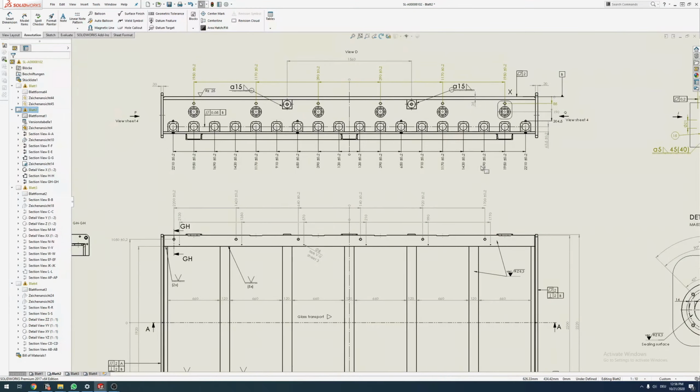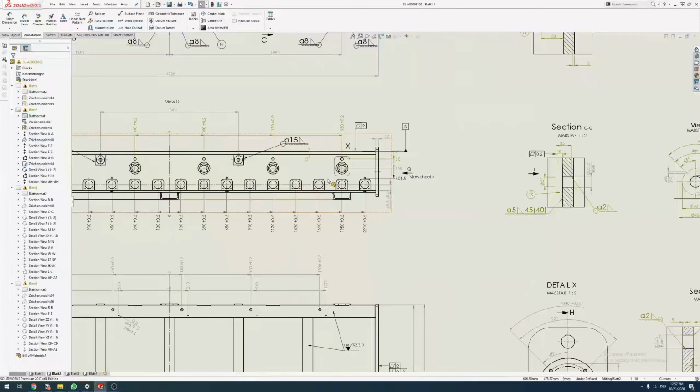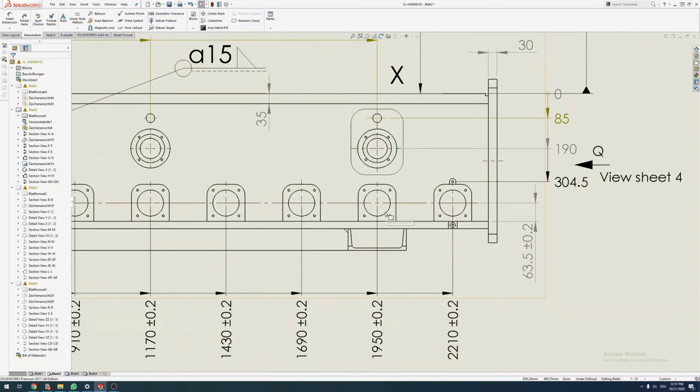You pretty much have to specify these measurements, because the way it works is first they collect the parts, then they weld the structure together, then they drill these holes and a bunch of other things like these. These wouldn't be drilled before the part is already welded.